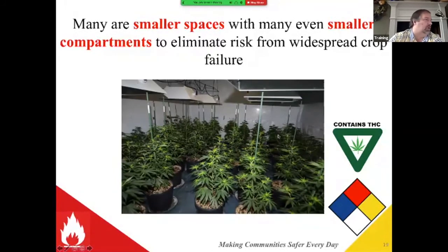Now, I don't know what they have on the walls in this particular location. I can't say for sure, but from a building inspection standpoint, we need to make sure the wall coverings are in compliance with flame and smoke ratings. And they like to get creative as to what they put on the walls. They want something smooth, easily cleanable. In this case, it looks like it's almost a form of insulation with the vapor barrier on it. Vapor barrier probably is a good idea because these are humid areas. Maybe it would prevent moisture traveling into the construction of the building.